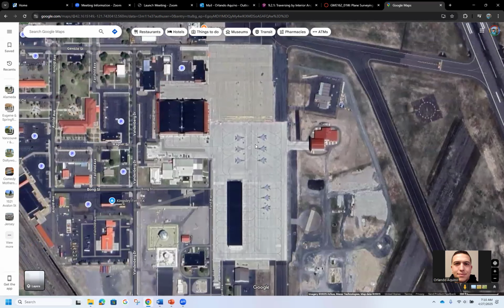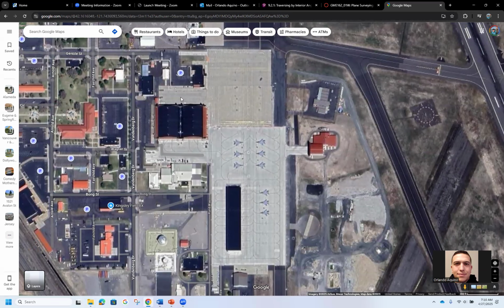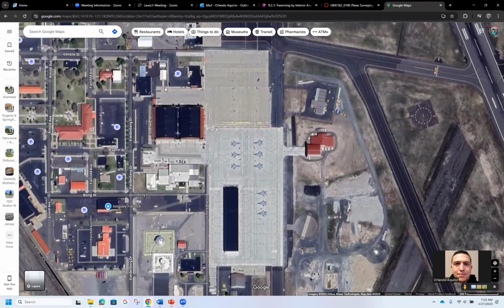And then we had to run the adjustment to make sure that the raw mesh closure was good. It was in tolerance, and then we had to run an adjustment through these points that we ran through to get a closed traverse, or an adjusted traverse, for this entire project. Once we got that traverse down and we got the control down, we started the topographic survey. And again, the topographic survey had to be really tight, and the control had to be really tight in order to have really good data for the topographic survey, horizontally and vertically.